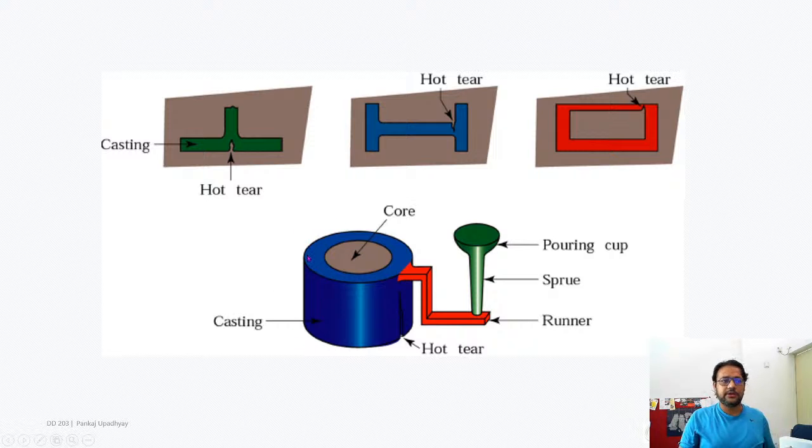When it started cooling, if you think about the outer layer of the whole thing, it gets pulled in a certain direction, the direction which is getting cooled faster. And when this kind of pulling force comes into play, you'll get some spaces which get tears.